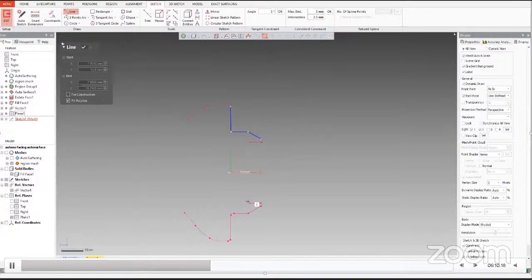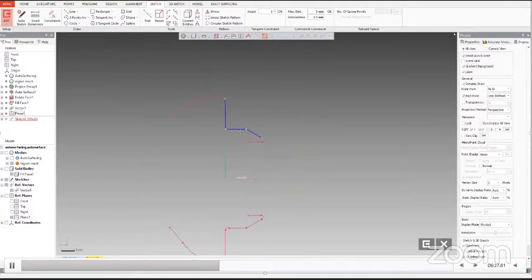So since it is a revolve feature, I won't go to the bottom section to make a sketch. I will make only half of the sketch and then use the revolve command to rotate that profile about the central axis. We can see the lines have a green color at the ends, and they are small dots.